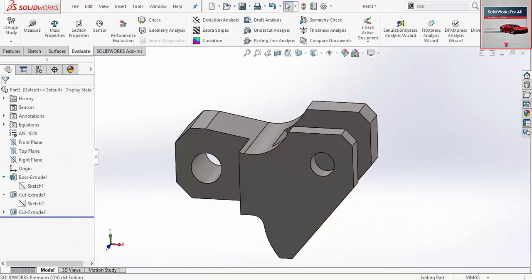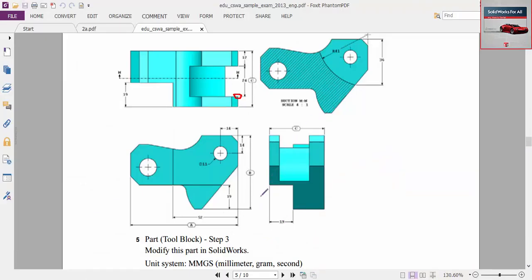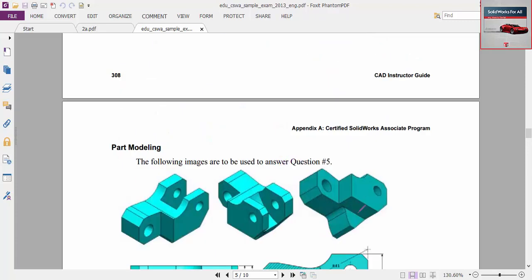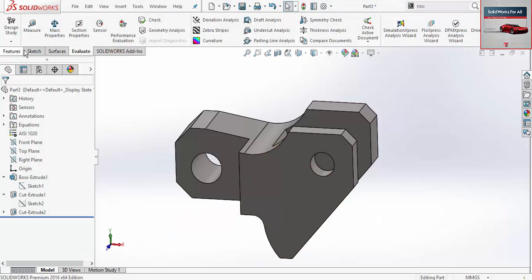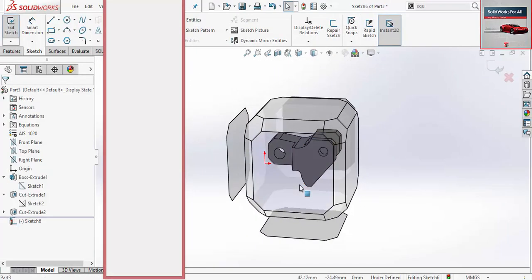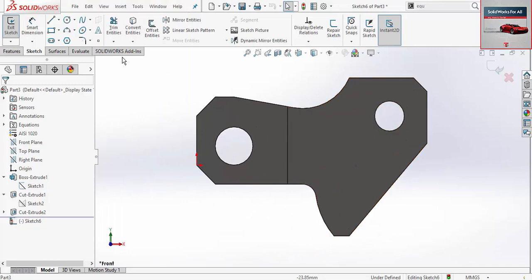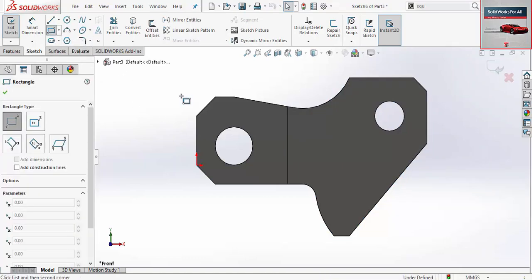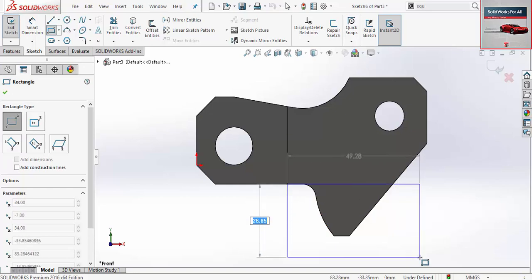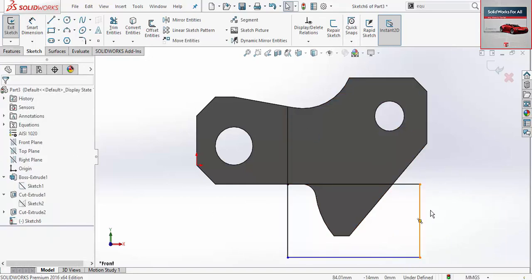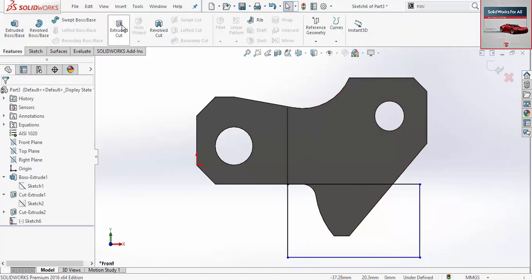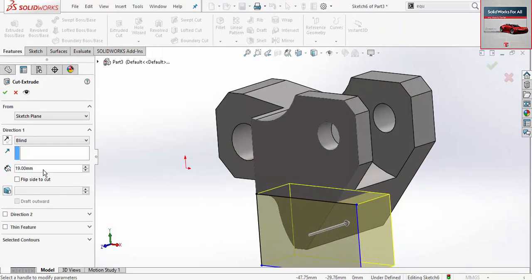So after that, if you try to see, there is an extrude cut that happened there. So we will do it. I will make a sketch on this face and try to be normal to this face, and try to make convert entities, or you know, we don't need to make convert entities also. We can make something like that at this point, and there is no dimension there because it covers all the area that we want. So we make extrude cut by 19, okay, and make yes.